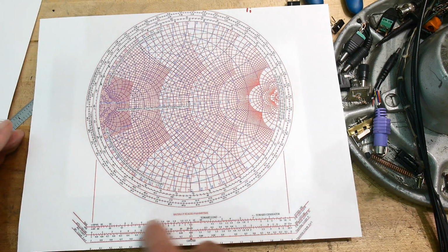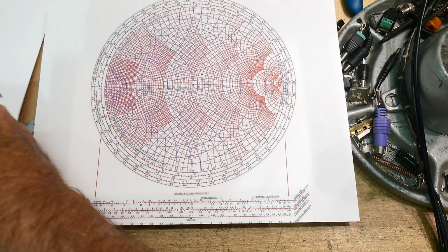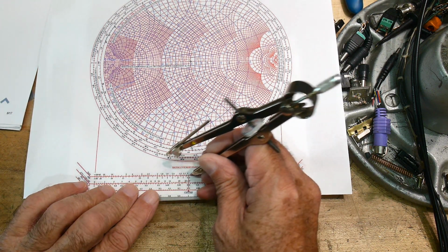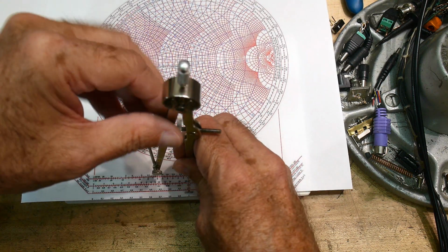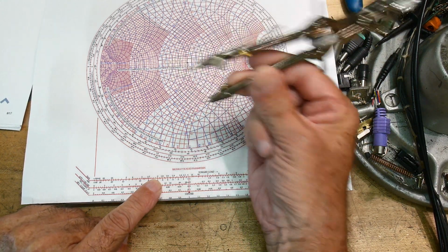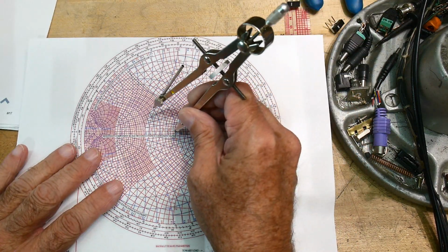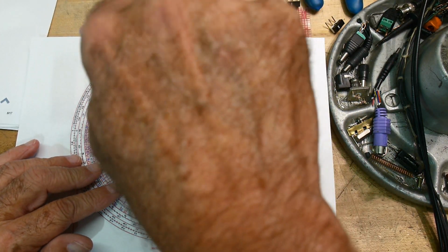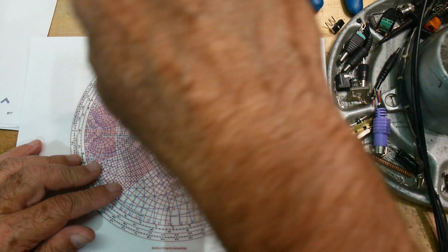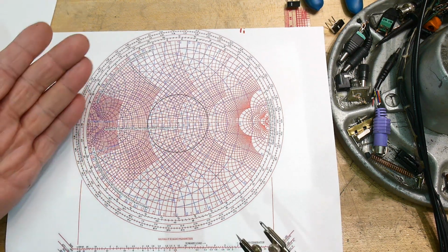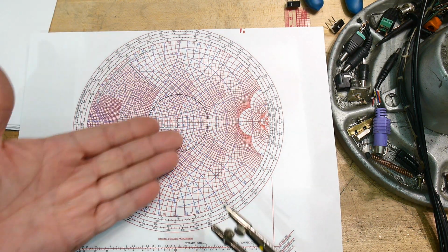Now on an official Smith chart, let's go back to this one here, there's these scales at the bottom. Remember I said you could use those for certain things. So this one is labeled SWR. So we're going to put one point here at the center, and I'm going to put this exactly at 2, okay? That means that this is now set to an SWR of 2. So if I put it here in the center, and I draw a circle, I've just drawn a VSWR of 2. So if you're inside the circle in your Smith chart, you have a SWR of 2 or less.